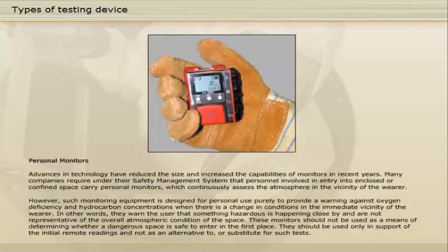These monitors should not be used as a means of determining whether a dangerous space is safe to enter in the first place. They should be used only in support of the initial remote readings, and not as an alternative to or substitute for such tests.